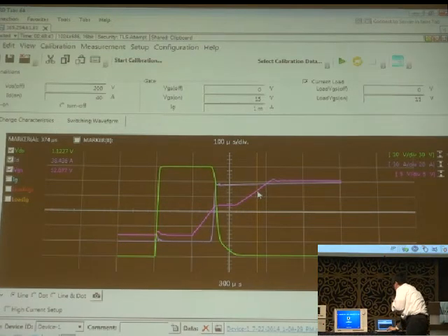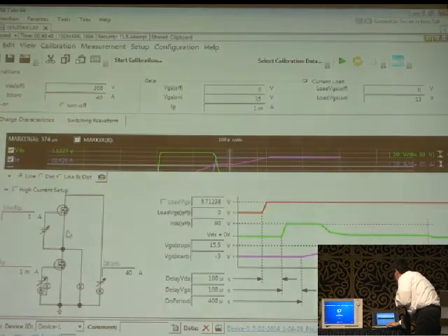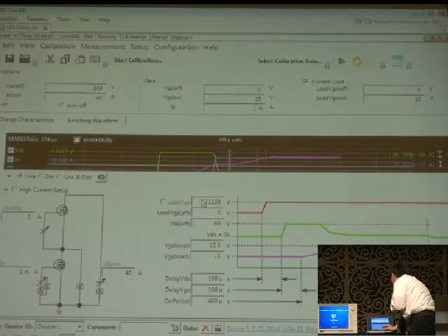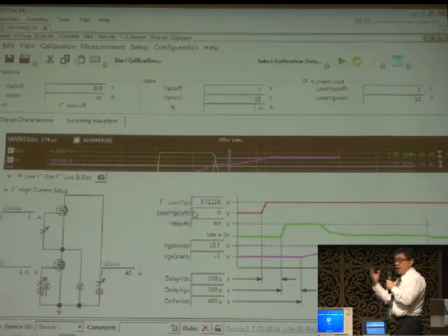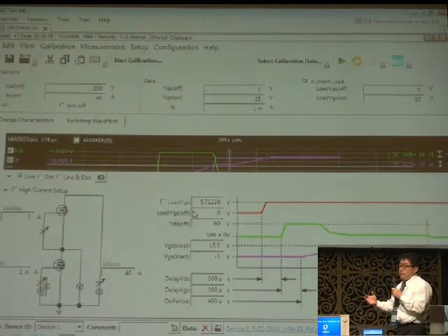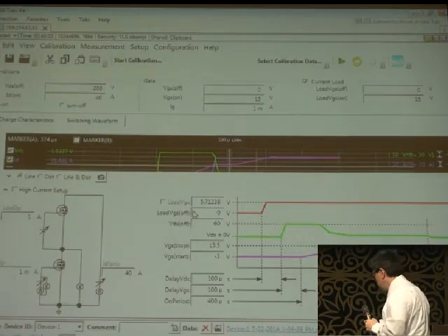The gate voltage of the current load FET is automatically adjusted at 5.7 volt to make the on current at the specified value. So users do not need to care about this kind of adjustment. It's quite easy.